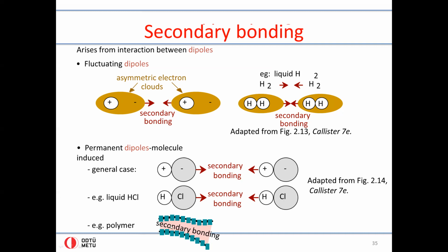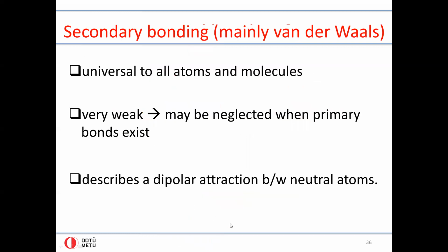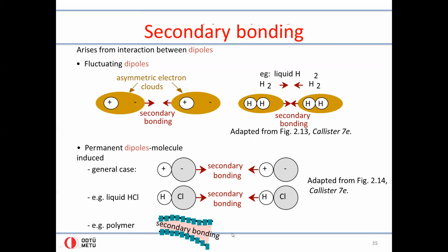So the idea is, if you say, is a polymer strong? The answer is yes and no. So a polymer, like a plastic bag or a PVC pipe, is weak enough that you can separate one chain from the other because they are not bonded strongly. But it is also strong enough that if you try to break this chain, it will resist tremendously. So then another important factor in polymers becomes how these chains are arranged and how they come together.